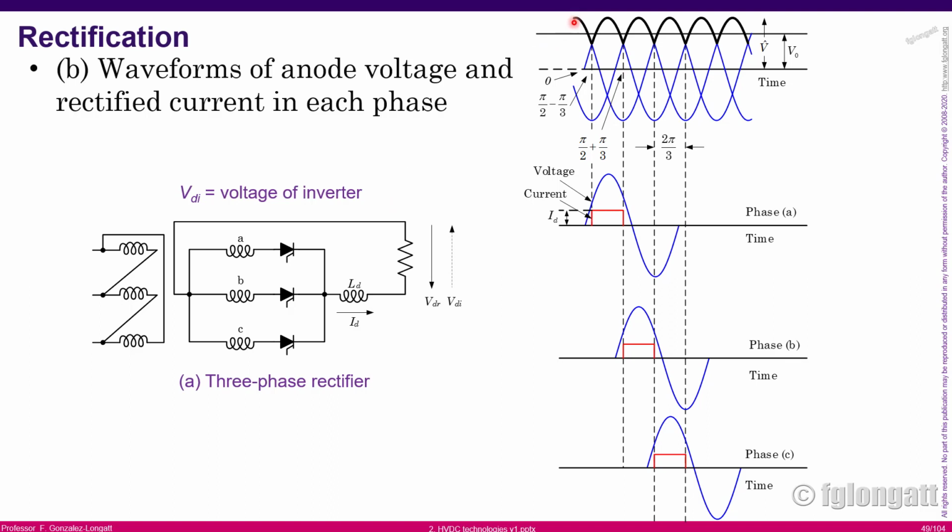What I'm telling you is we have here three different signals, and when we are switching those devices, we are closing the device and then the device opens, and we have this black line over here representing the rectified voltage, okay? This is the total voltage that is rectified at the very end, and as you can see over here, this is the current for phase A, the current for phase B, and this is the current for phase C, and they represent three different locations because the signals are triggered at different times, okay?